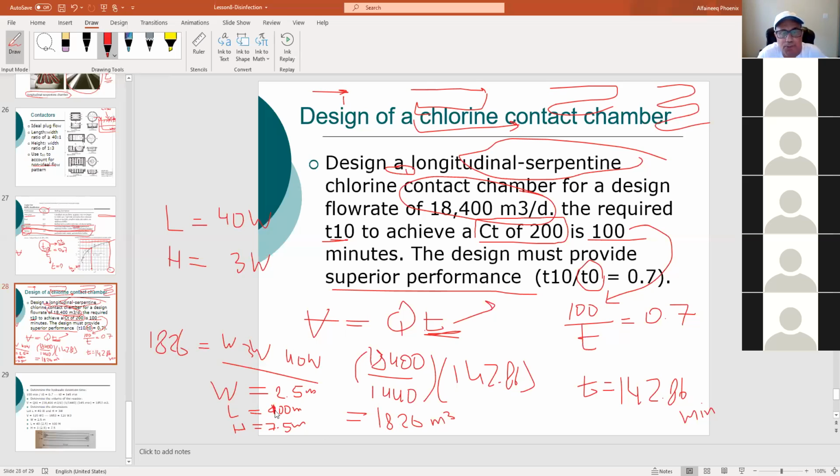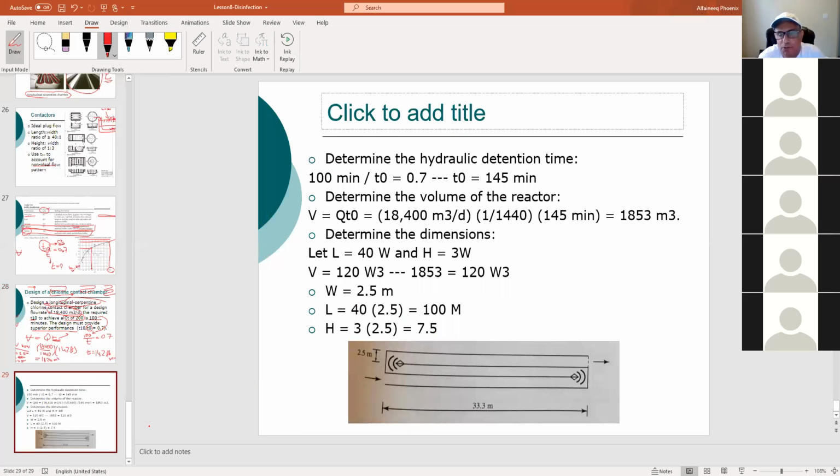Maybe you will have enough space, no problem, do it in a straight line. But in this case, it's a good idea to do it in 3 as you see. Each is 2.5 wide, as you said, and 100 total, divided by 3, so it's going to be 33.3. So from here, 33.3 meters, makes a U-turn and comes back again, another 33.3, then from here goes out. That's a total of 100 meters.